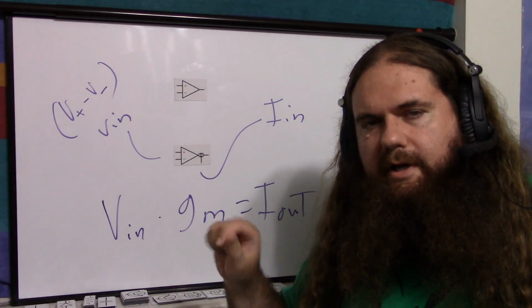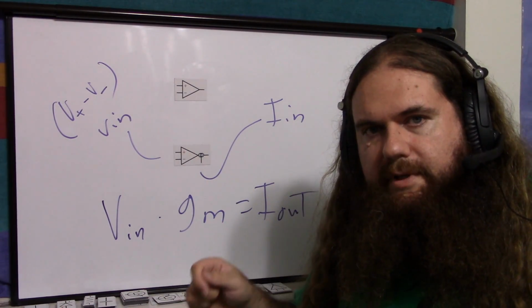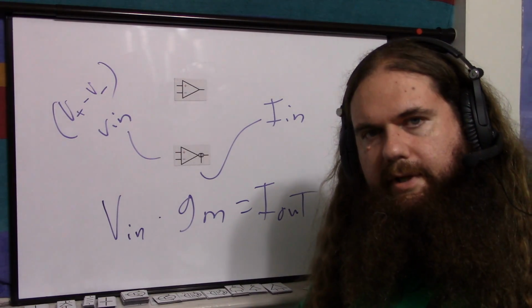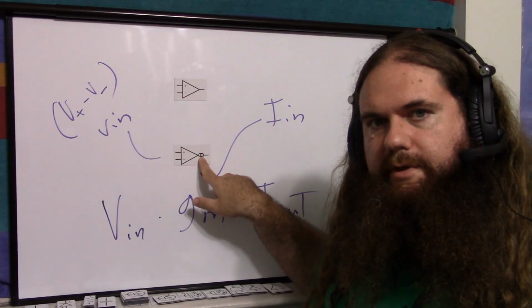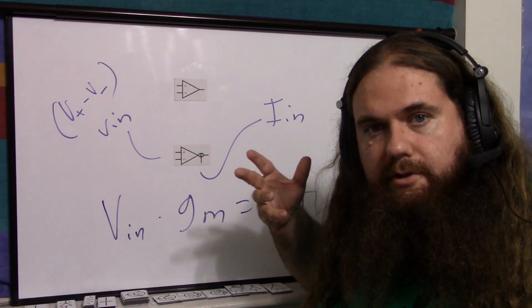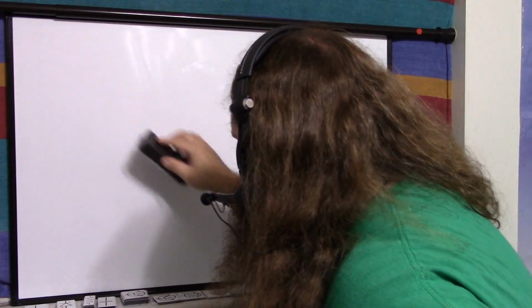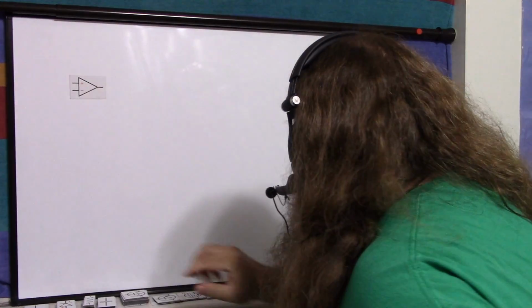You turn the current up and down into this pin, and that turns your transconductance up and down, which turns your output current up and down. And we've discussed it's a current source. That's what these two little circles are. Two little circles, wherever you see it, is a constant current source. It means the voltage varies to keep the current constant. So I'll go into detail on that in a moment, but I want to mention one thing.